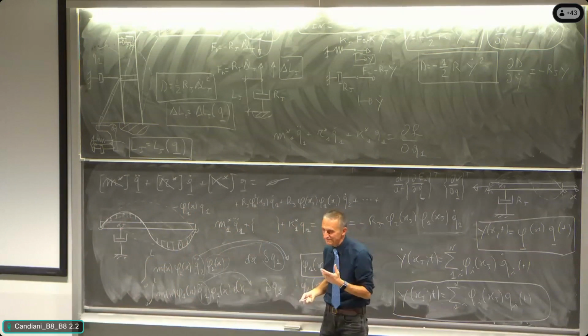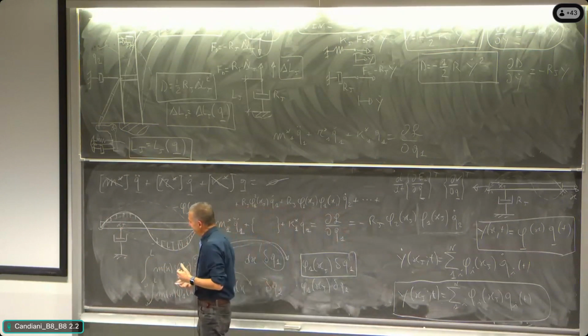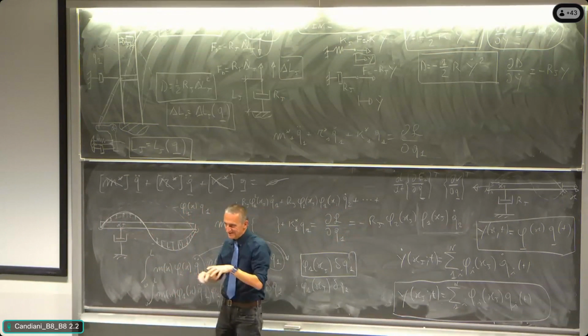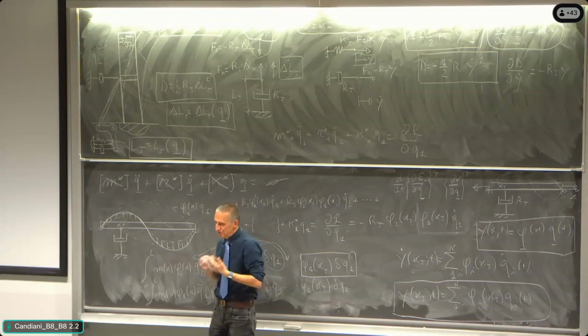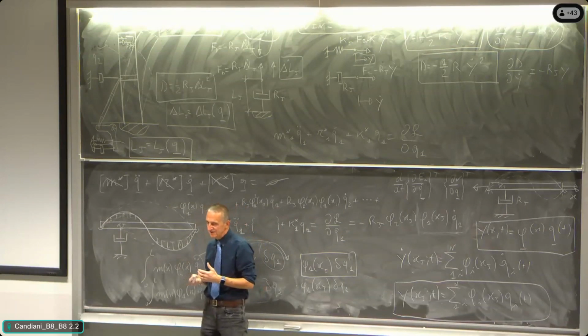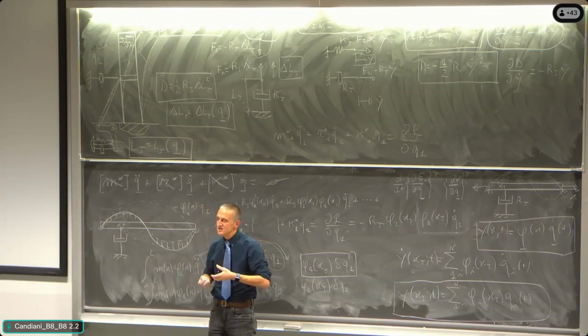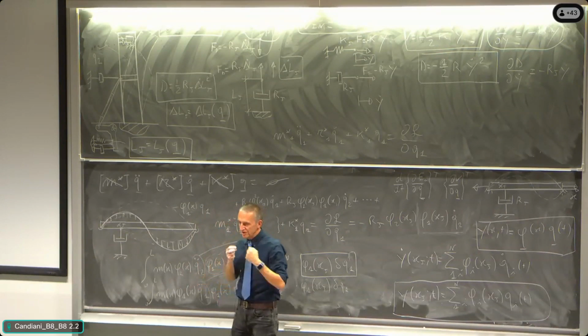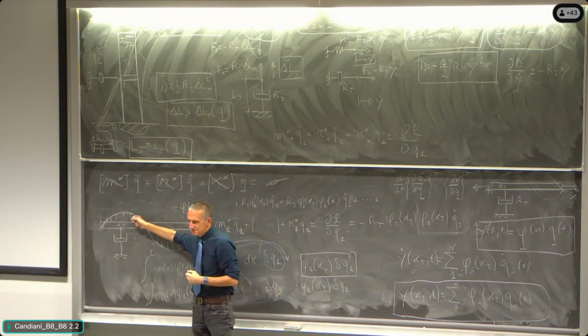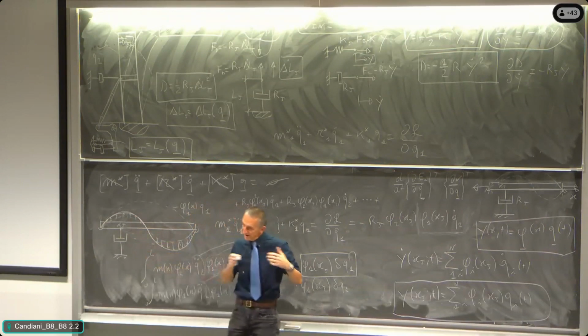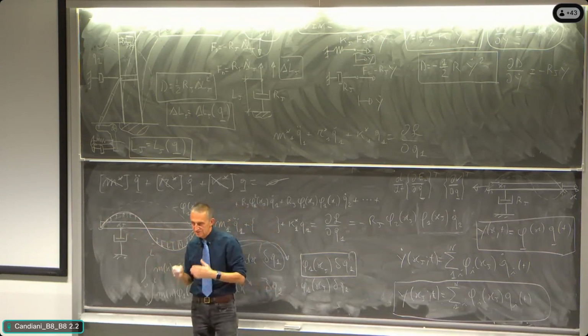Where is the damping? The damping is just constrained by saying that we are assuming that the distributed dissipations associated to distributed internal action in the material are proportional to the distributed mass, and proportional to the distributed stiffness.